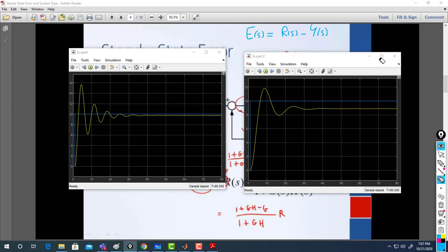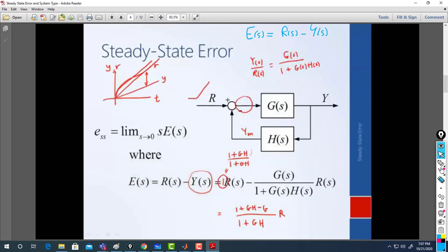So we saw it in simulation. So what's the trick here? What if I have, as Rami said, a sensor dynamic, and my sensor is not one, as always? Then this is not the error. When I ask the student where is the error, they tell me this is the error. And this is wrong. The error is still the same.